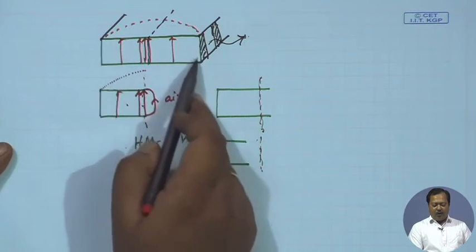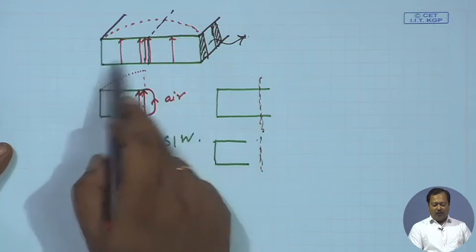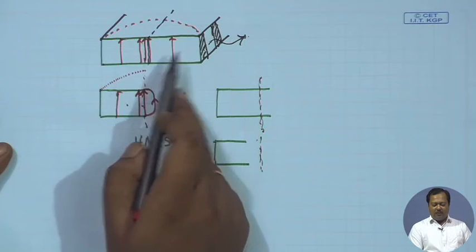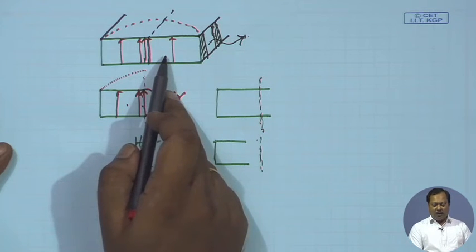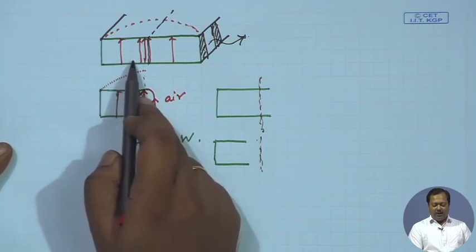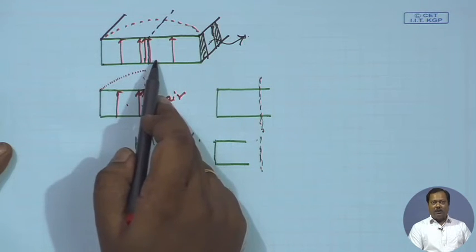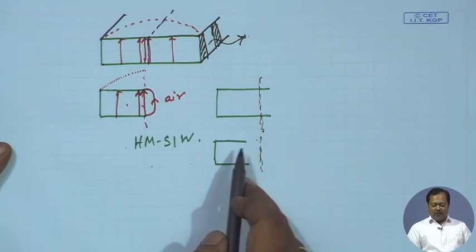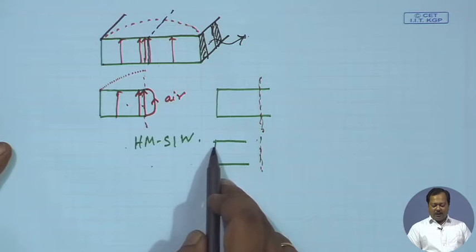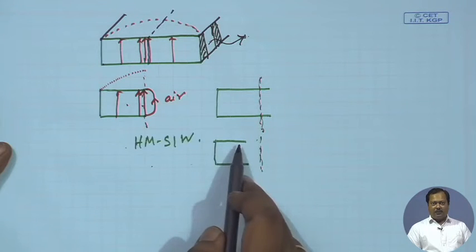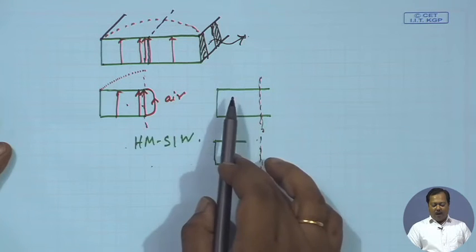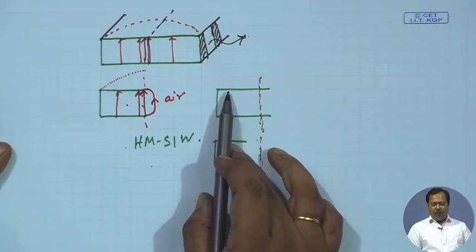Not only that, you recall that beta of any given rectangular waveguide depends on the width of the structure, right. So, if I change frequency for a given structure, beta will change, or in other words, at a given frequency if I change W, then beta will change. So, beta becomes a function of the width of a rectangular waveguide. For this type of structure also we can control beta by changing the width of the structure.